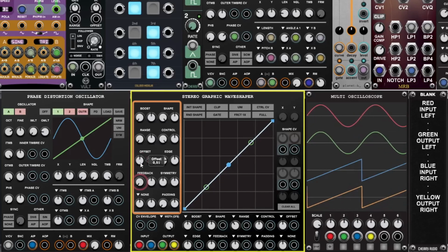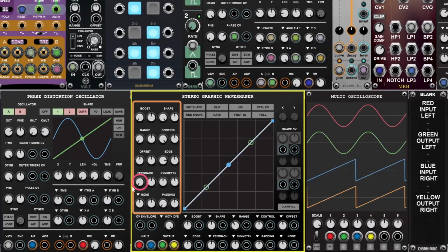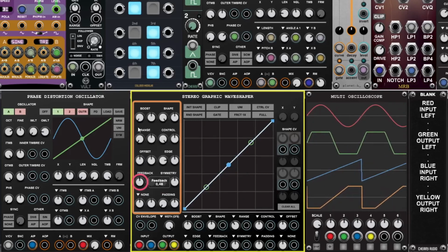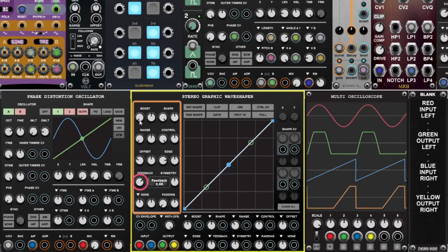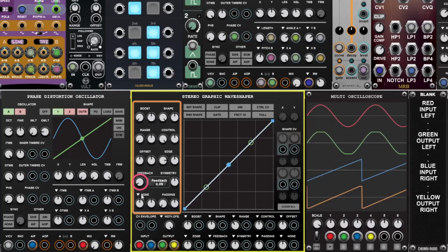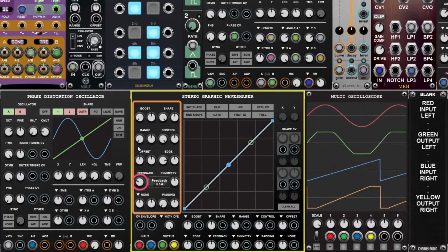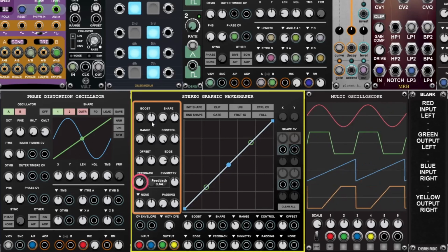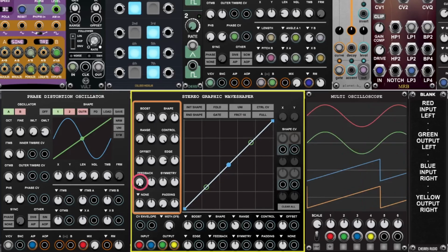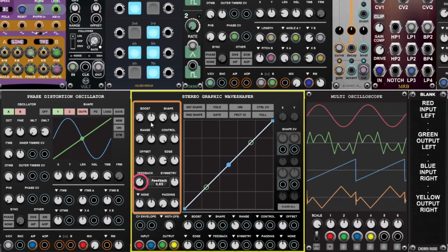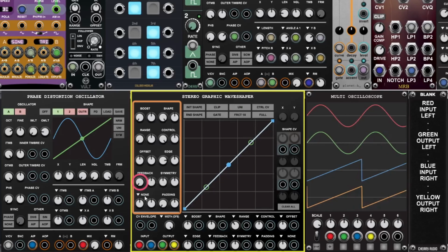The feedback knob controls the amount of signal that is taken before the shaper and fed back into the input signal path, right after the boost and offset stages. This signal is combined with the input, and this cycle repeats indefinitely. The feedback knob acts as an attenuator in this case. However, you never need to worry about out-of-control feedback loops, as the clipper folder stage is inside of the loop, keeping the level under control before it finally goes through the shaper.